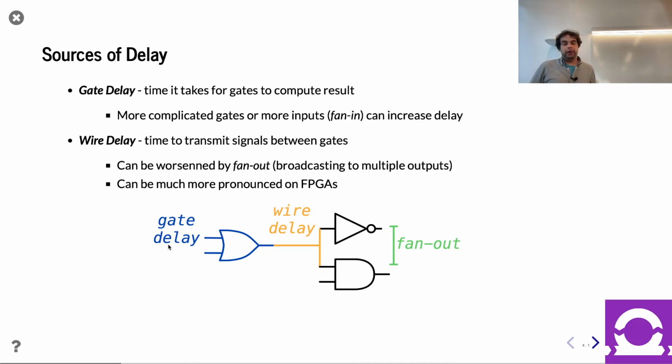Good question. So the wire delays are worse than FPGAs for a few reasons. Number one, as you said, was the routing, where because the routes are reconfigurable when you put on different bit streams, that flexibility causes some circuit conditions, right? So there's some stuff there. Additionally, also remember that FPGAs are, unless you're using the hard blocks, going to be less dense, right? So the things you're connecting are farther apart from each other. So it has to travel physically farther. And rather than being a perfect, custom wire for that one connection, it's actually a route through a switchable network, right? The network is statically switched in advance by the bit configuration, but yeah, that flexibility adds some latency as well as the far distance adds some latency. So it kind of gets you both ways.